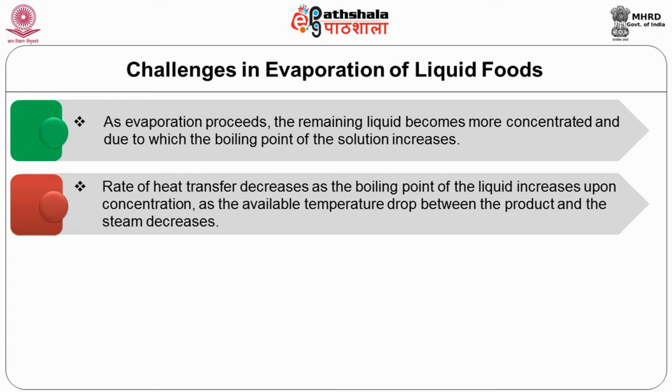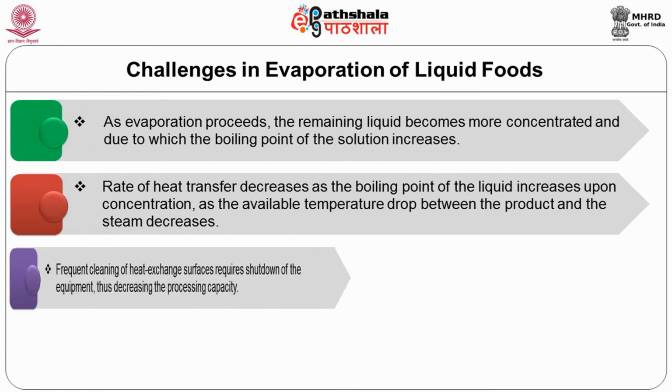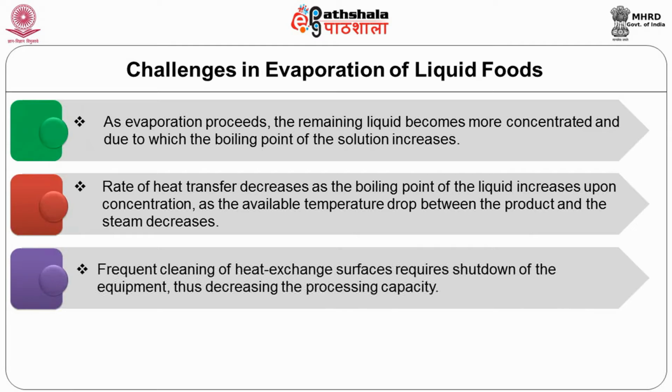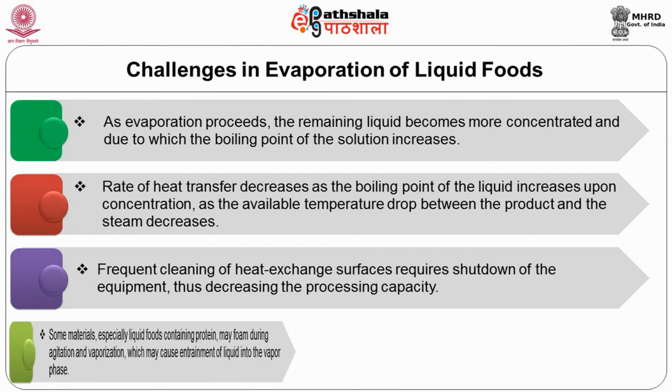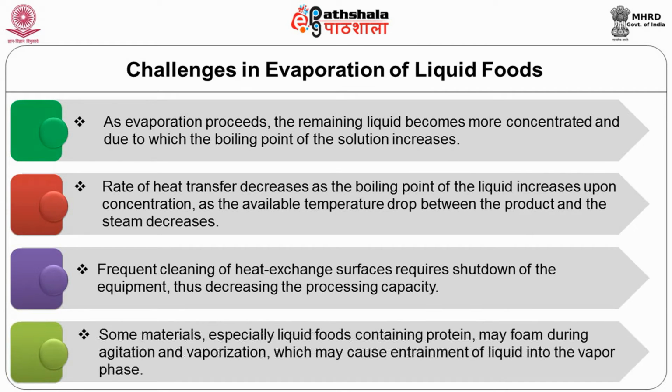Fouling of the heat exchange surface can seriously reduce the rate of heat transfer. Frequent cleaning of heat exchange surfaces requires shutdown of equipment, thus decreasing the processing capacity. Some materials, especially liquid foods containing protein, may foam during agitation and vaporization, which may cause entrainment of liquid into